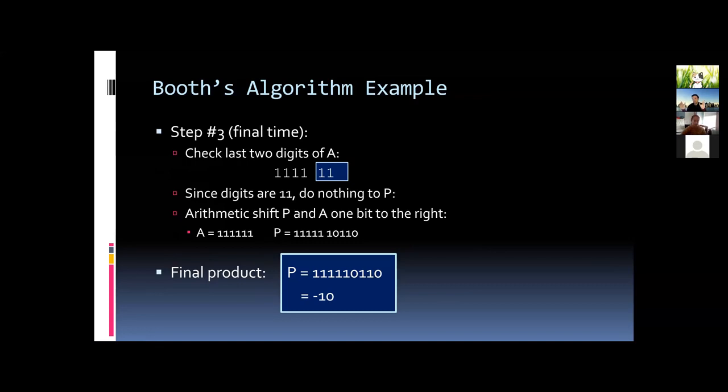And that's when I do the trick, right? I convert this 1110 into all ones minus that value, and essentially do subtraction. The subtraction compensates for all the ones I've seen before, right? So I don't need to act because I'm delaying my action on all the ones.